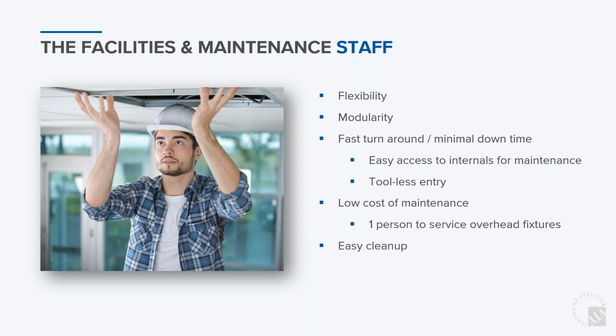So they want easy access to the guts of the fixture, toolless entry, and generally only one person coming in to service the fixture. And so what you'll see a lot of times in patient rooms is that the fixtures are all room side access. That is a huge deal in these specific rooms, because you think about if somebody had to get into a plenum space of one of these patient rooms, well, you literally have to shut the patient room